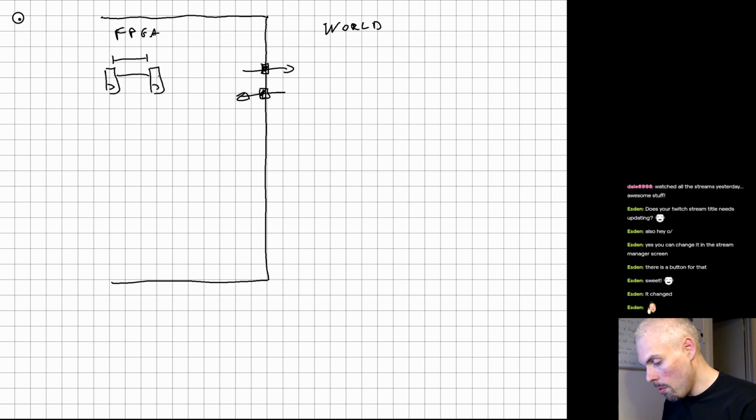It actually takes time also for a signal to go from an internal flip-flop through the I/O buffers, because at some point here you have a buffer that's going to convert from the V core to the output voltage, and to actually appear outside of the FPGA on the pad, right?